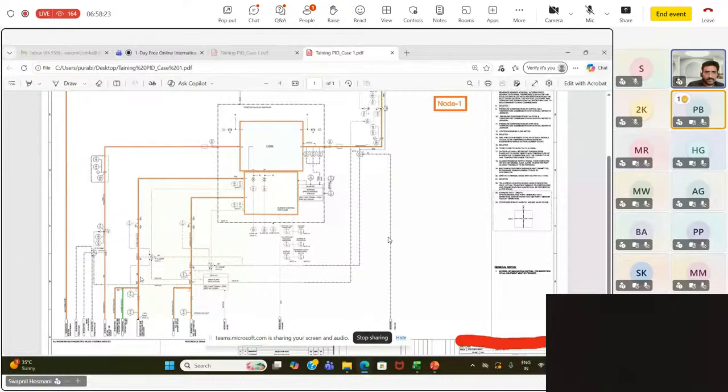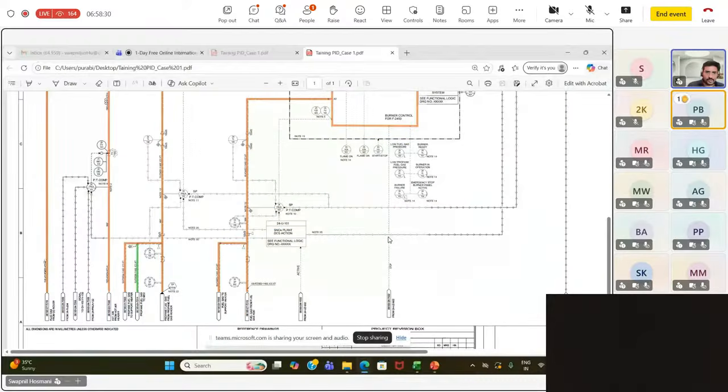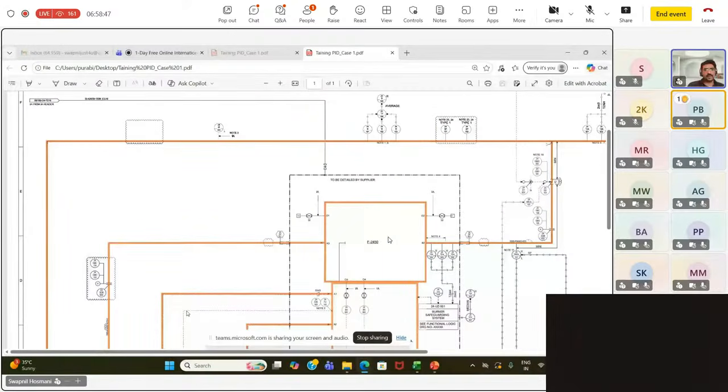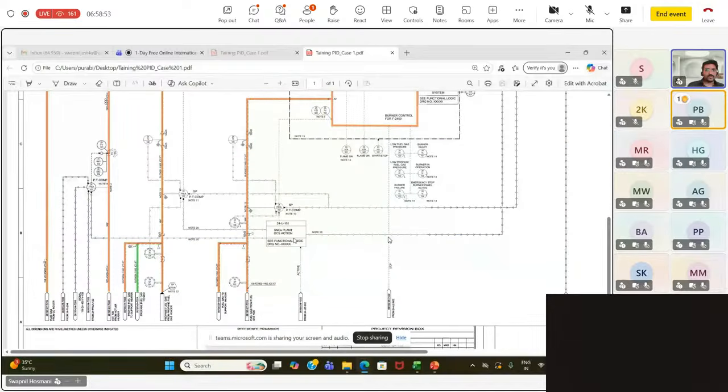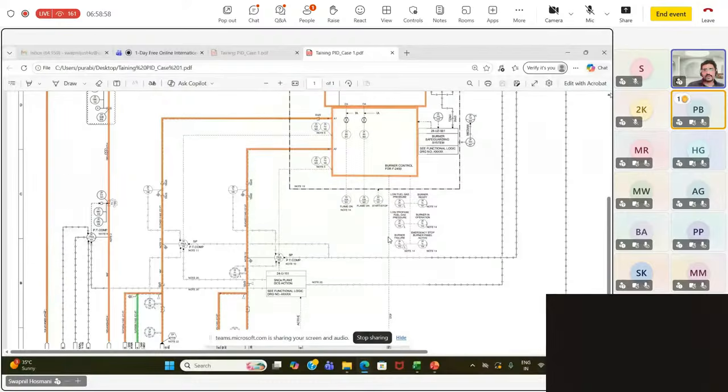One is ammonia, right? This is ammonia, is it? And the other is fuel oil. One second. Yeah, so one fuel source is fuel gas. And the other source is propane fuel gas. And this one is hot air from the air header. So what they are doing is, this is the flue gas which is passing to the downstream system. They are taking a slipstream from this flue gas and passing it to the startup heater, which is heated by propane and fuel gas.